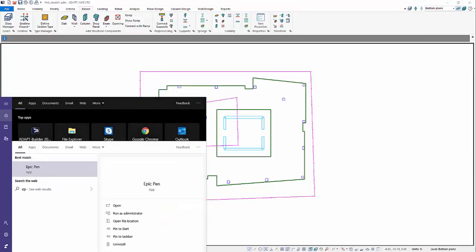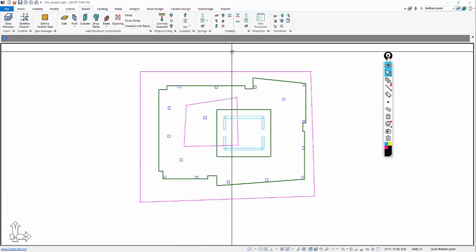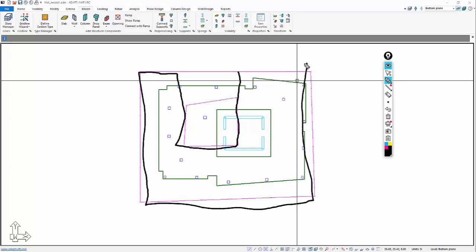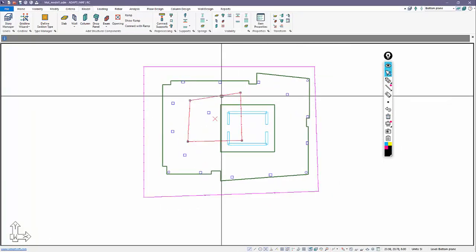So I'm going to go ahead and show you what I mean here. I'll open up a marking tool, and rather than have these overlapped, one region might look something like this. This would be 2.7. I would create a second region of 2.7 and then another region of 5. So we have 1, 2, and 3 regions. This is how you would set it up for multiple spring values in a single model like this. Okay, we'll go ahead and delete that.